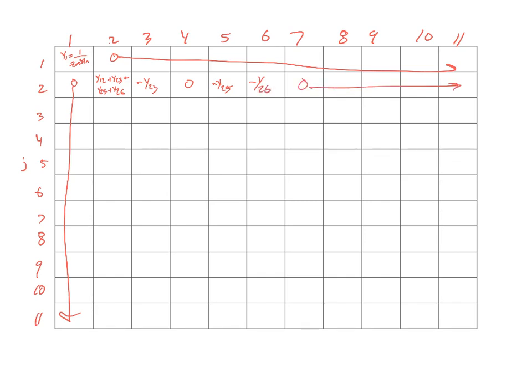So again, I can see here that I have a Y12. Now this is not 100% symmetric matrix, and that's because there is no connection between bus 1 and 2. So different from the positive and negative sequence diagrams because you actually don't have a connection. This ties to reference. So in effect, this is the same thing as saying this is a self-admittance connected to bus through. It is the transformer impedance that goes to ground.